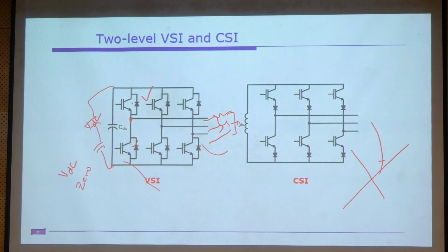So here, if one device has 4 volts and the other device has some 2.5 volts, that means the 2.5 volt device will be turned on early. So all the current will be bypassed through that device, and it is not capable of carrying that, and the device is damaged. So to ensure that, what we normally do is, before connecting them in parallel, we have to make sure that their threshold voltages are equal.